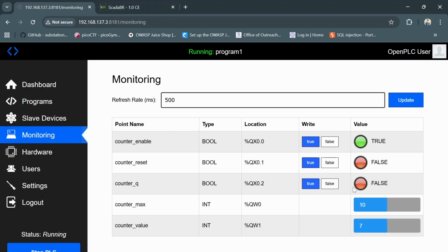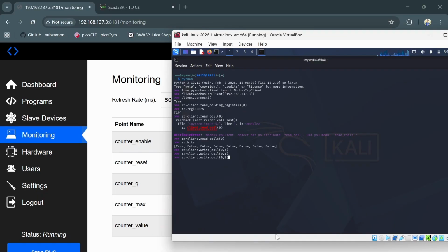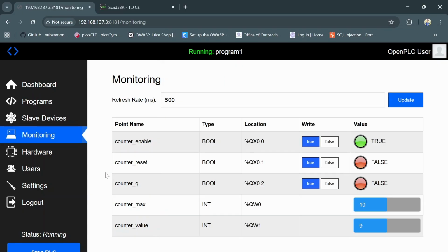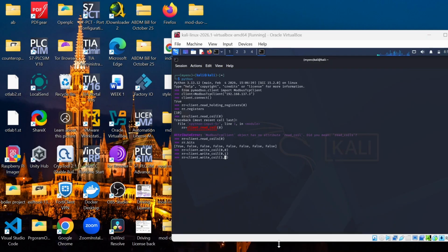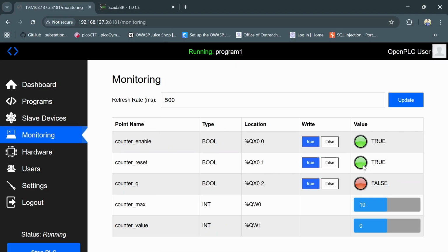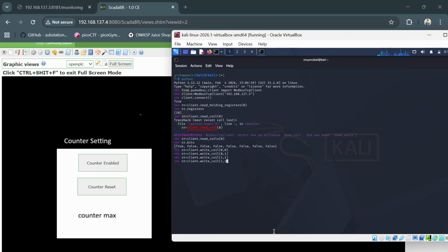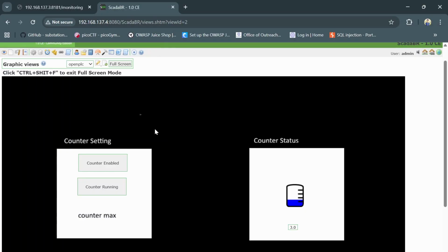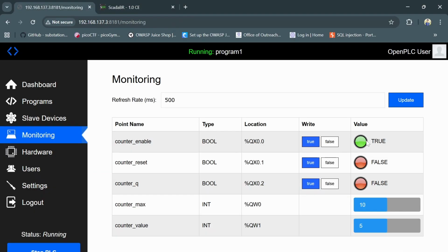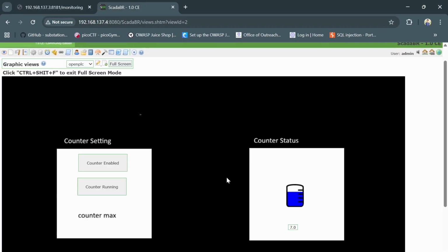So Modbus TCP on port 502 is very vulnerable, and we can secure it using segmentation in our networking, making VLANs, and using firewalls, industrial firewalls, etc. So we should make our industrial systems secure by using these techniques, like using the Purdue model, which segregates different components in different zones.